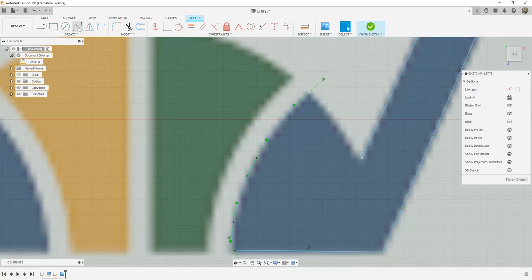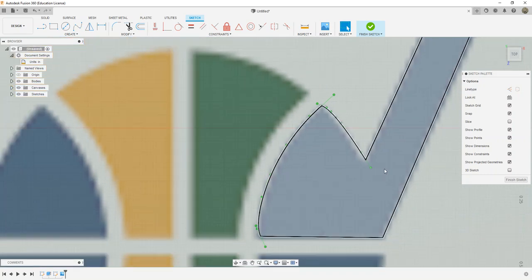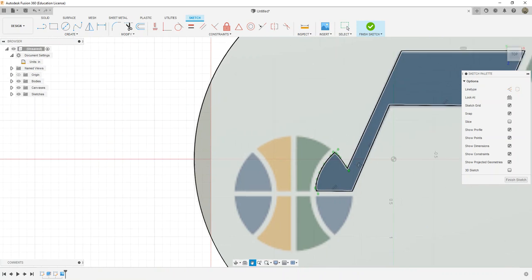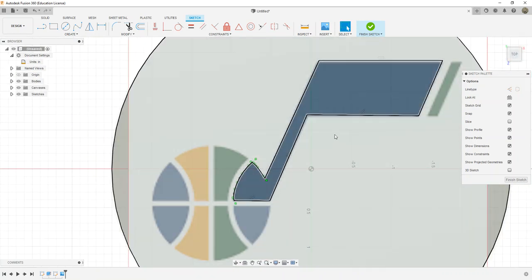And then I'm gonna go back to it again and snap it back to where I started. You need to have a closed shape here. So I just snapped it there, enter. You see how that lit up, is highlighted when I hover on it? Now I know that that is a shape. It's important that you have closed shapes when you're doing this.